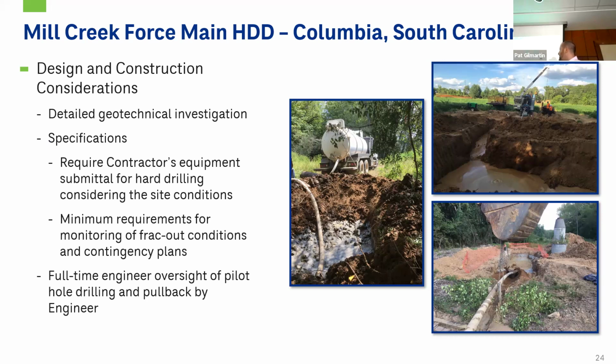Like we considered, there were concerns about frac out. So near the end of the alignment, we did get one singular frac out here. You can see the mud and the gray. They ended up building a berm of soil and got the excavator in there to contain that. And then that fracture was able to heal after about an hour of downtime, and they didn't have another frac out for the rest of the alignment. And so one of the keys there was we did have full-time oversight of this by one of our junior geotechnical engineers to ensure that things were moving along adequately, and they were able to address both the frac out and the hard drilling conditions fairly quickly.